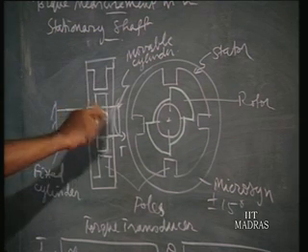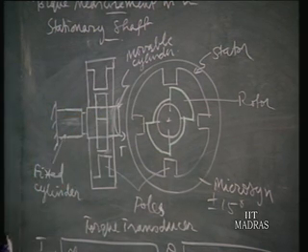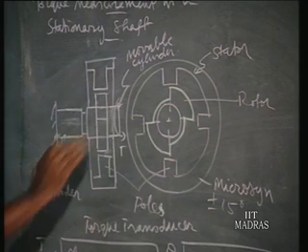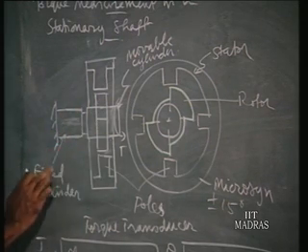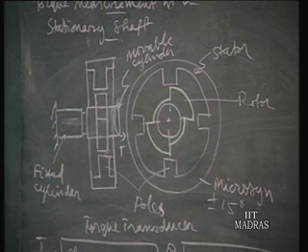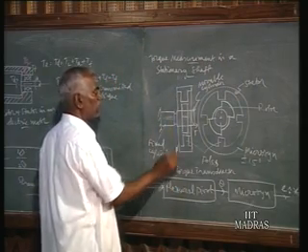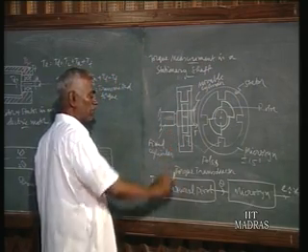Now the torque is converted into angular rotation by these cross leaf springs. So this cylinder assembly, with the fixed cylinder and the 3 springs inside, converts the torque into theta. That is what is shown here, the flexural pivot with the cylinders. The pivot is inside.